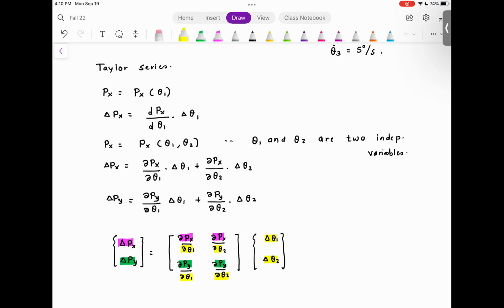Go to Sim Mechanics, which is the MATLAB toolbox. And if you go to Sim Mechanics, you will be able to construct the robots just by dragging the blocks. An alternate option is, if you have SolidWorks, create the solid model. MATLAB will import that solid model into Sim Mechanics and create the joint structure, the robot assembly for you inside MATLAB. So if you want to play with it, I'm going to stop here and we will continue the discussion next time.